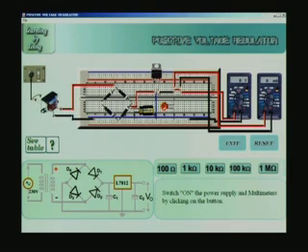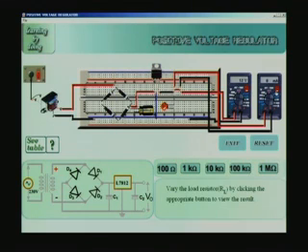So I connect it to the breadboard here, and I have a bridge rectifier here, and a transformer here. Now I switch on the power supply and I switch on the voltage and the current meters. Now you can see the output voltage is 12 volts, and because I have not connected any load, the current is 0. If I now connect a 100 ohm resistor, you will find it is around 120 milliamperes. Because this is 100 ohms, and 12 volts is the output, I get 120 milliamperes.